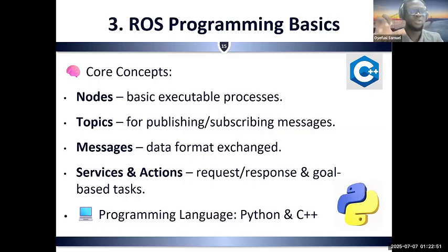All right, so messages, so subscribing messages. Messages are the data in the topic. For example, in the scan topic for LiDAR, you have numbers, a kind of data format exchange. I would explain this during the workshop. We'll echo a topic. We'll do a ros2 topic echo slash scan. I'm just dropping some commands we'll be trying. Then services and actions. Basically, when you want to do something in navigation, you can send a goal, so ROS services enable you to do this.